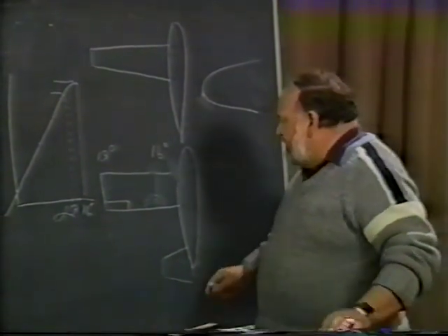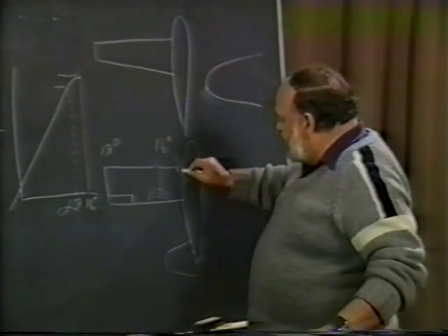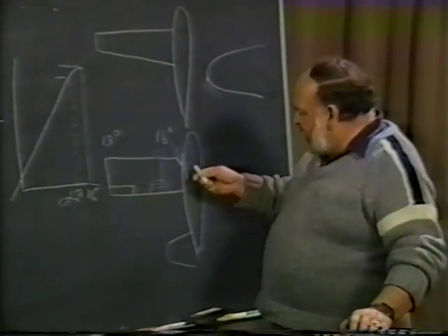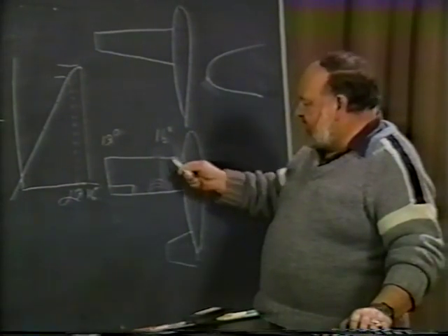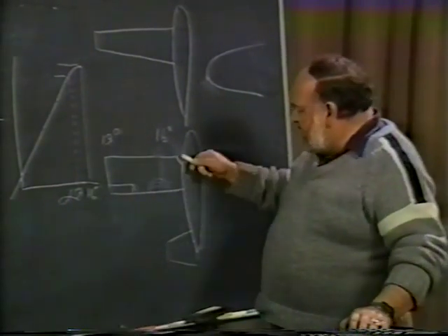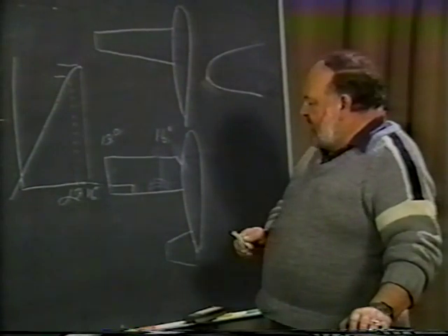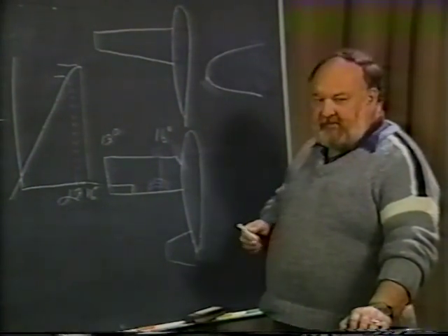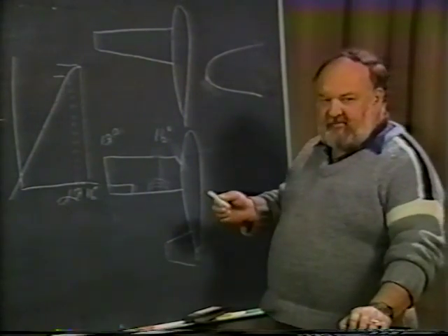one thing can be done, and this is where Steve Wittman was very brilliant on his design of his Tailwind. Take a look at a Tailwind and look at the planform. What do you see? You see a little notch here in the wing. You have the straight leading edge, and then you see a sweepback of the leading edge right as it meets the fuselage. Well, he's done it for several reasons, very cleverly.